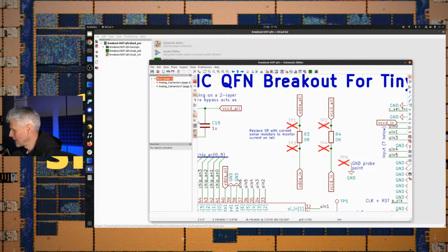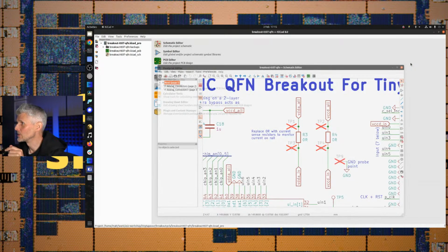So Sam is saying level shifters. That's a possibility. But I thought probably the quickest and most transparent way to do it would just be to use the system that we already have in place, because a level shifter that works with differing voltages on both sides is basically going to be a transmission gate, and that's what we already use on the analog side of the circuit. The way that I'm doing it is faster, but it is also more expensive because you have to pay an extra bit for each pin.